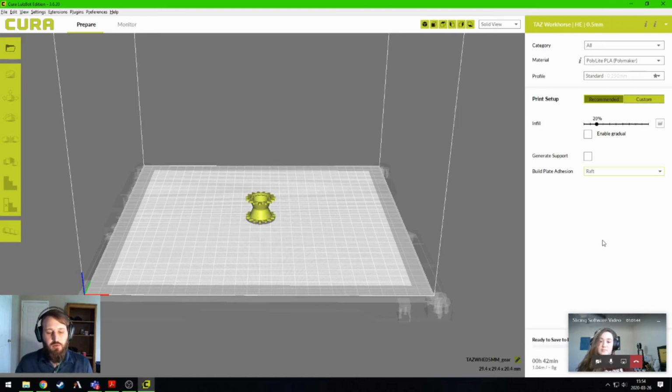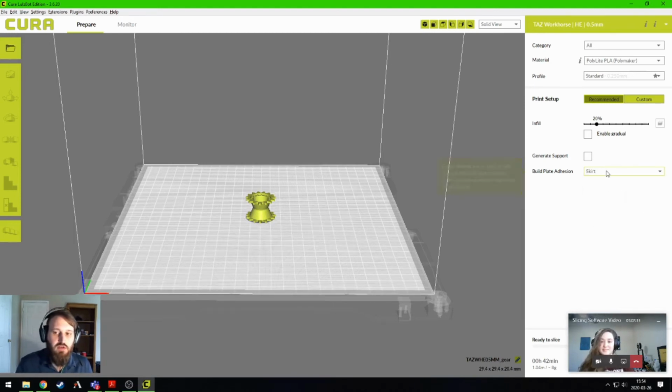It also can help with adhesion if you're just finding that these things aren't working. Putting the raft down might help because it adheres to itself a little bit better. So just having it do layers, even if they're messy layers, it's a raft. You don't really care. As long as it gets that raft started, and then it can print on top of that, you'll be okay. It doesn't matter if the raft looks pristine; it can be messy as heck, and as long as you get the adhesion, you're good. So it really depends on what you're working with. But if it's a flat object, you can use a skirt and probably be fine.